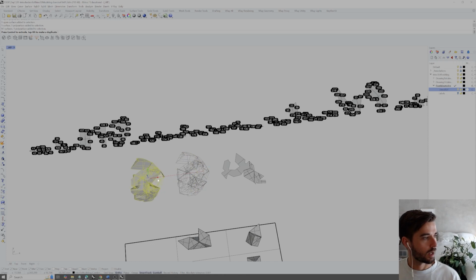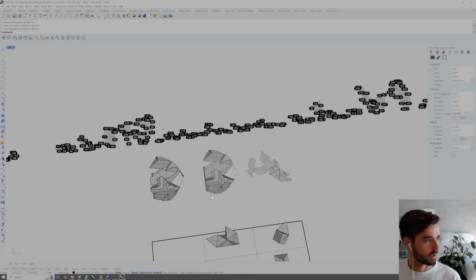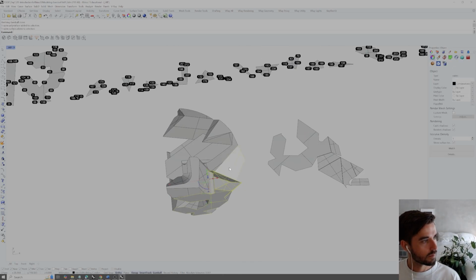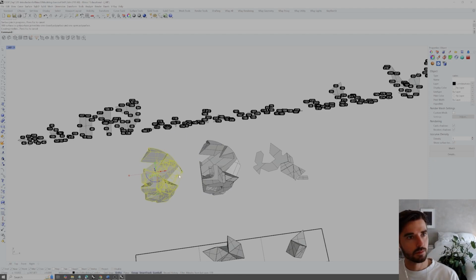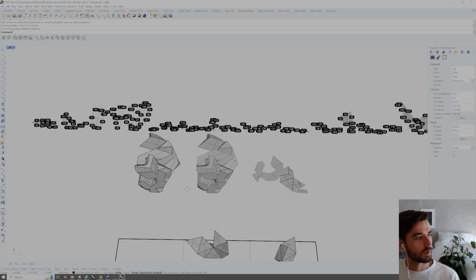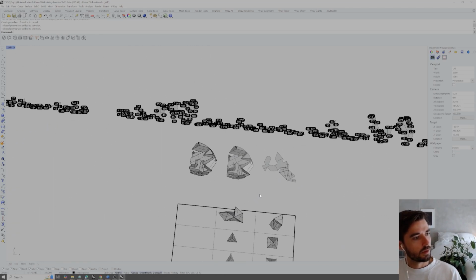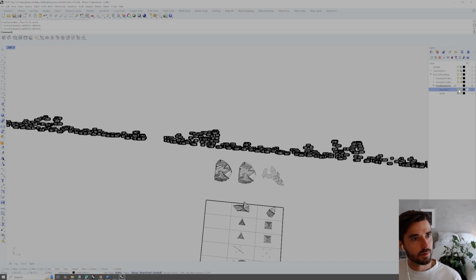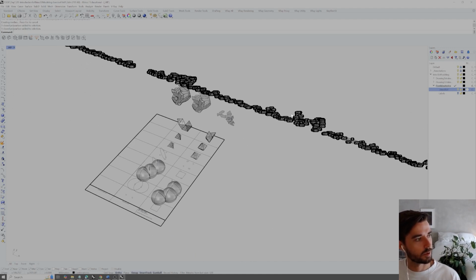I'm going to just go ahead and copy this over, join them all back together, merge all coplanar faces, and now we should have still it's now giving us an open poly surface. Okay, closed solid poly surface. Great. And okay, then we just have our unrolled surface geometry.